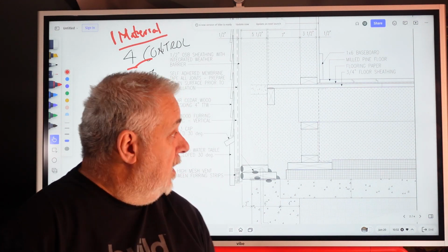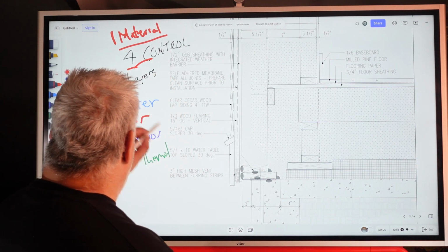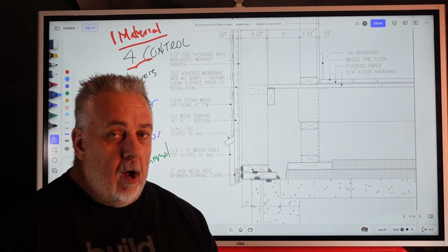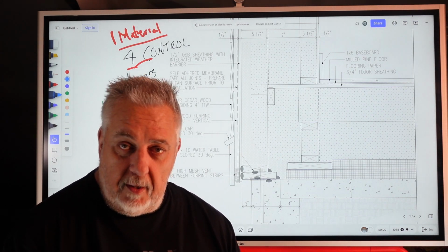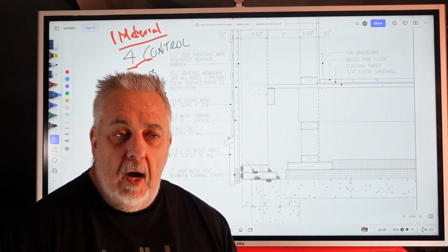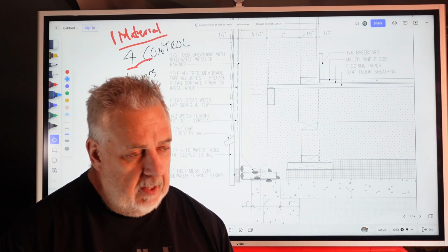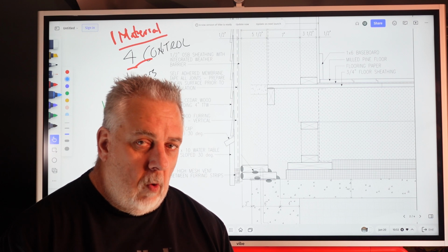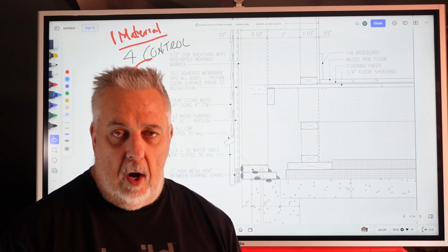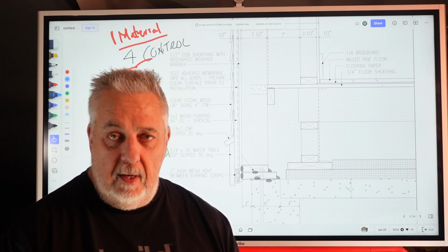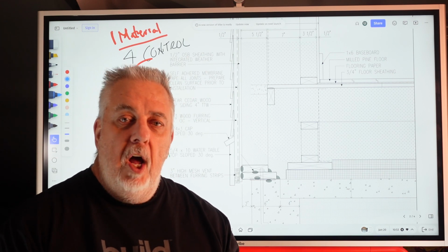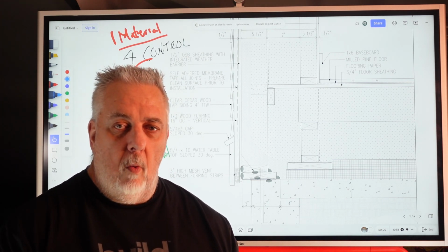So at the end of the video, I'll reveal the answer to that question, but I'll let you ponder that as we go. So let's talk about water first. Right? Obviously, water kills. #1 killer of buildings, right? If you Google the most litigated reason in residential construction, it is a water problem, water leak, flooding, something due to water. Water kills, and it's the #1 killer of building. If you want to build a durable structure, solve for water.